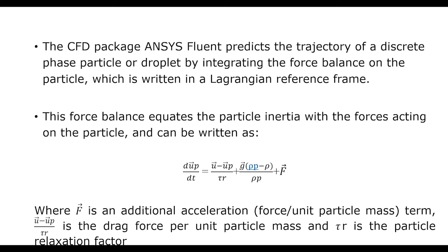When we come to this, tau represents the relaxation time for the particle. And this depends mainly on the viscosity and the drag law applied. Actually, the spherical drag law is applied for this setup because the droplet is expected to be spherical. It's not fast enough to be a disk, so it's considered as spherical rather than treating it as non-spherical.